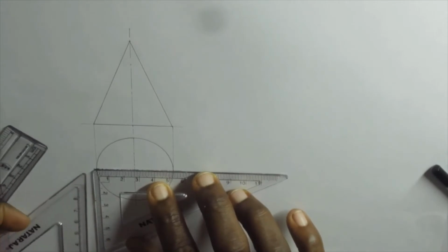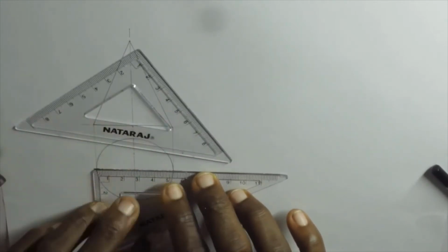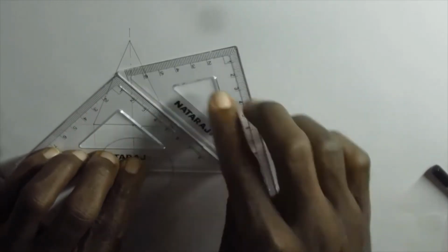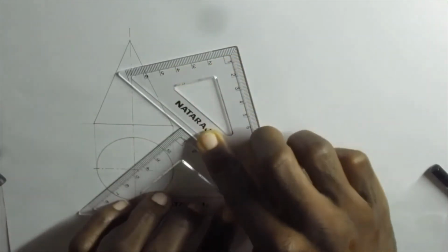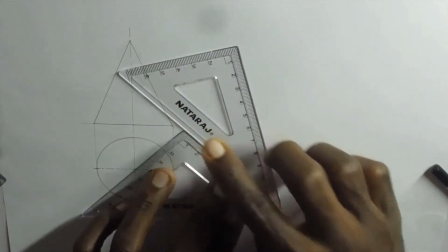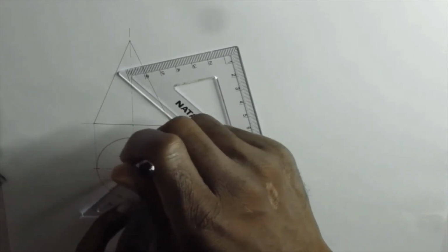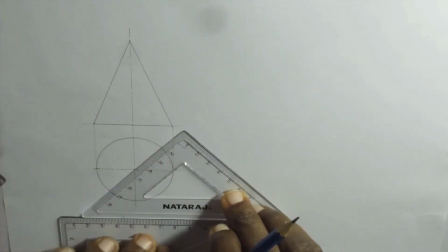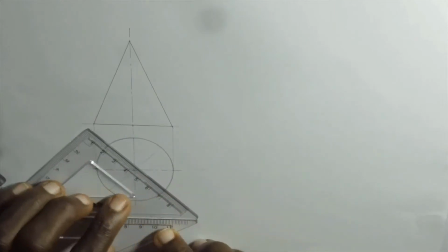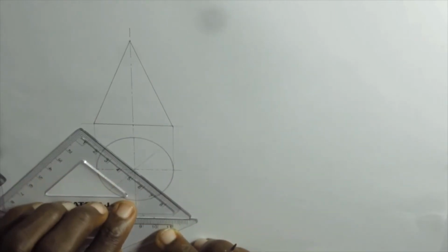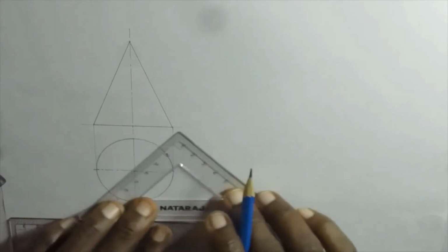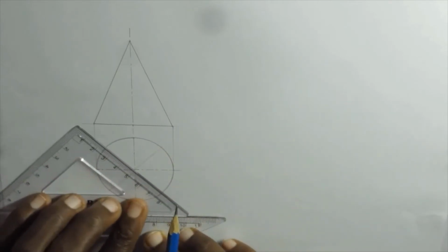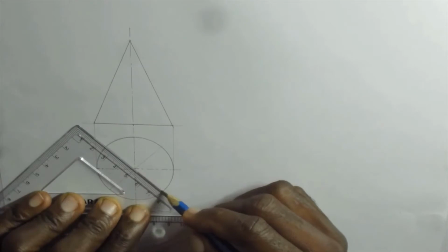All right, then after that, we have to divide this base circle into a given number of equal parts. I use 8 equal parts, so I divide the circle into 8. I have the center lines there, which form 4 divisions, so I divide each of the quadrants into 2. And I use the 45 degrees set square to do that. So with the 45 degrees set square, you draw a line through the center. Right, so use the set square to achieve that. So you can divide it into 8 equal parts.